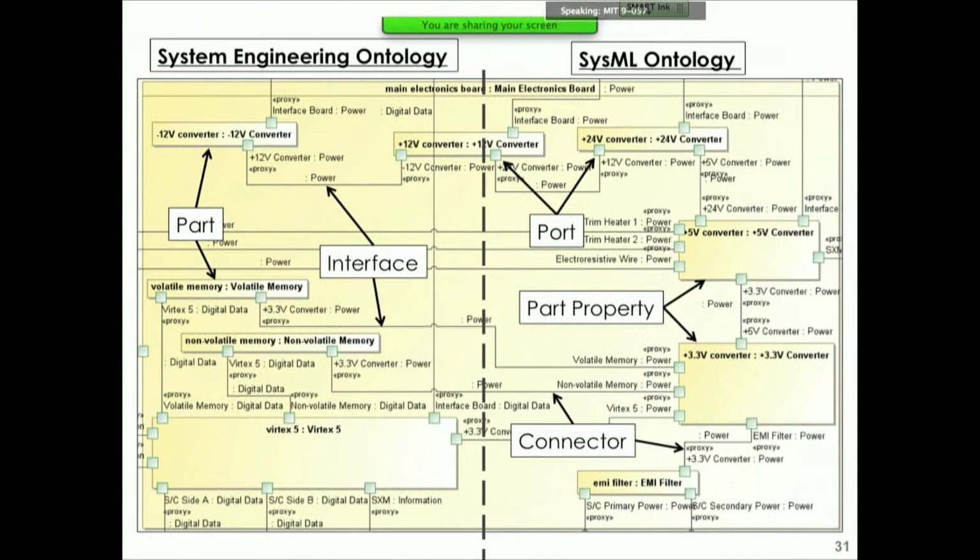And you could, for example, check that you don't have any empty ports. If a part needs an input voltage, you could run a script that checks that all the parts have all their ports kind of satisfied. That's something you can do with SysML.